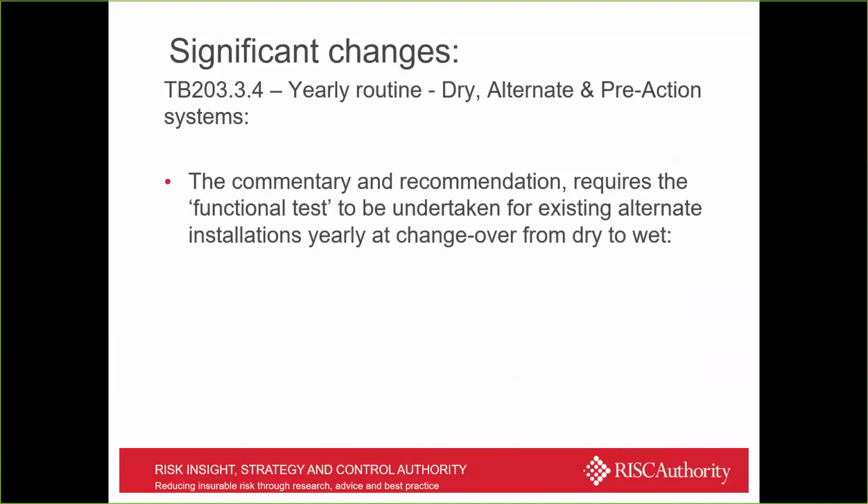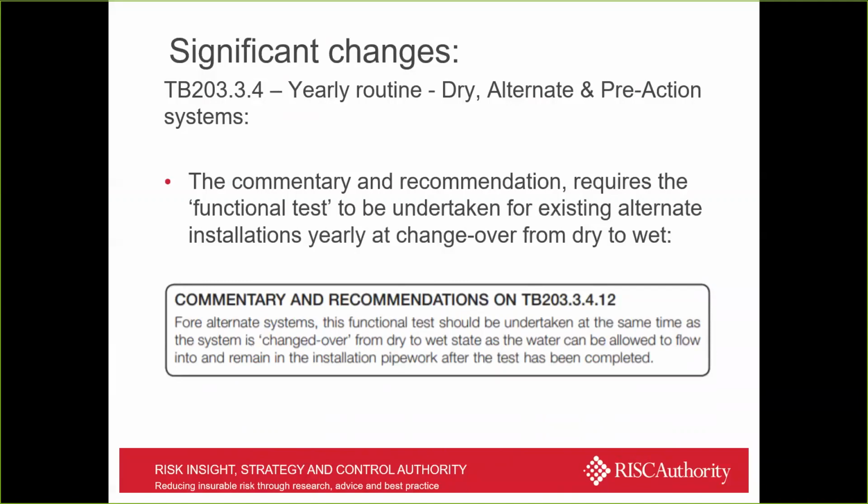The commentary and recommendation requires that functional testing to be undertaken for existing alternate installations can be carried out at the changeover period. So you can actually do a functional test, a full sort of fire test with an alternate system when you convert in the spring from dry to wet, and you can physically trip the valve. But for dry and pre-action systems, that's not really the case. So we've got the commentary and recommendation there that confirms what I've just said.